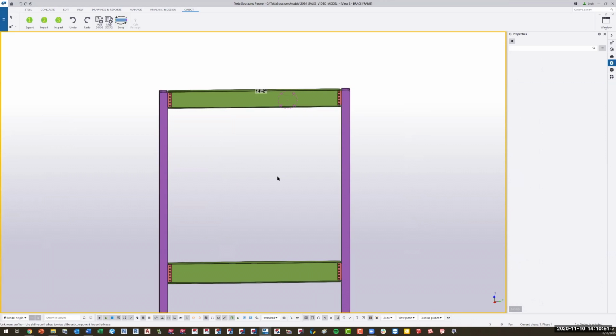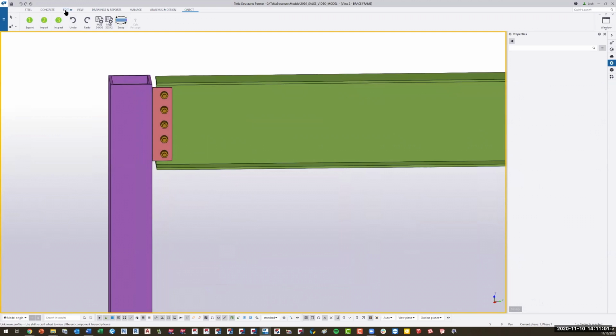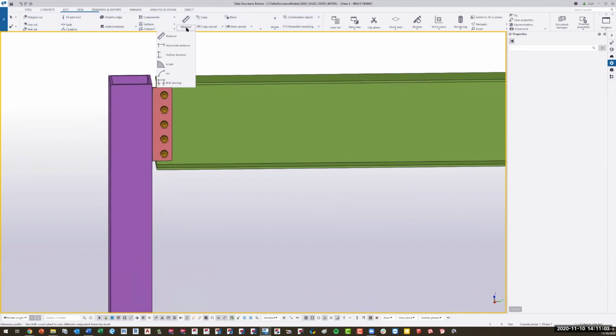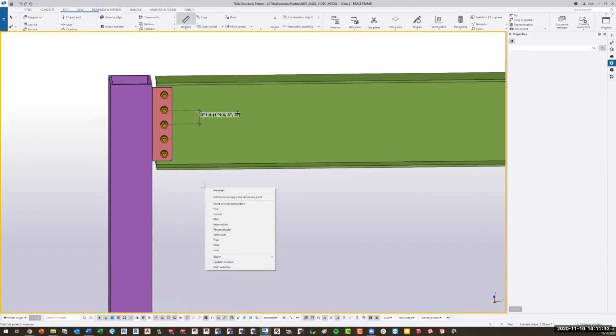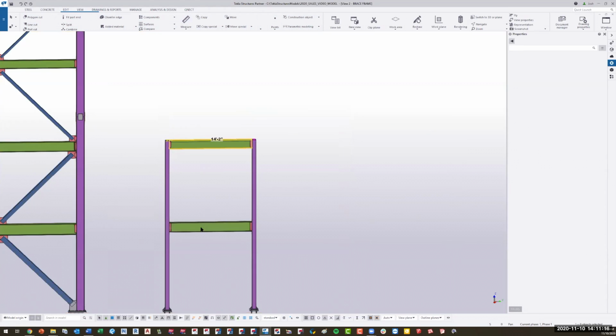So what if we want to reduce the length or even thickness of these shear plates? Reduce the weld length, the volume, but also what we have at Qnect is reducing the quantity of bolts simply by adjusting the vertical spacing. As everybody is typically used to, you're going to see vertical spacing of 3 inches on center. Okay, so you have your 3-inch vertical on center, but let's go ahead and adjust that.